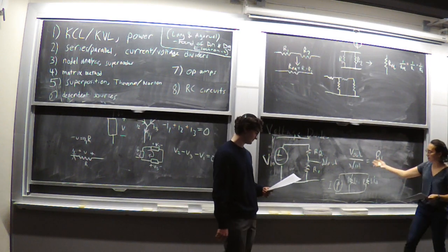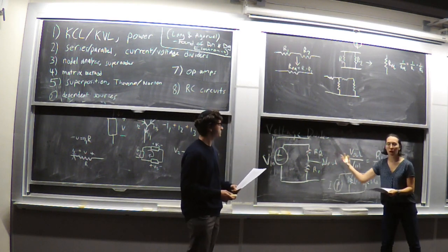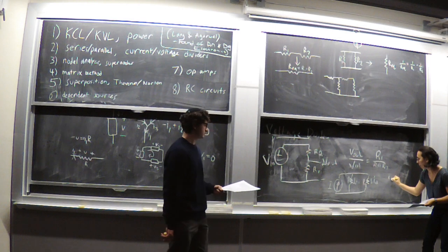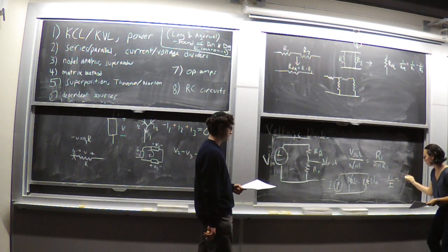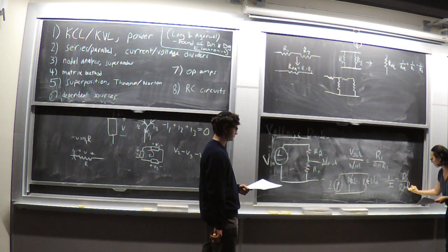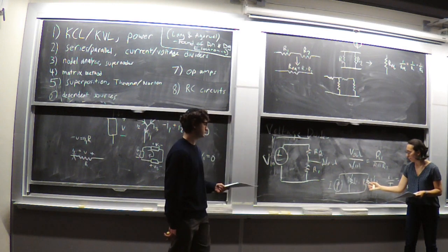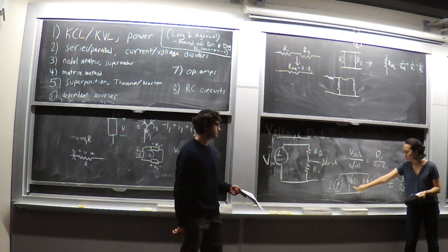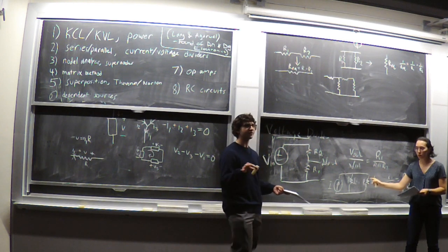So in this case, we had this nice proportionality. It was the ratio of what we were looking at to the total amount. In this case, we have that I1 over I is equal to the other term, R2 over R1 plus R2. Intuitively, if you think about an electron traveling through this path, it's easier for the electron to go through the I1 path if there's more resistance on the other path. So, path of least resistance, right?